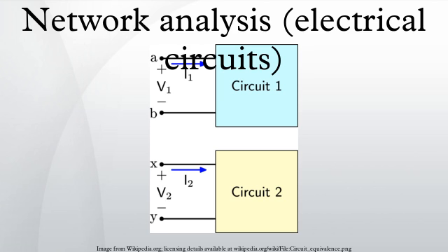Time varying components. In linear analysis, the components of the network are assumed to be unchanging, but in some circuits this does not apply, such as sweep oscillators, voltage-controlled amplifiers, and variable equalizers. In many circumstances the change in component value is periodic. A nonlinear component excited with a periodic signal, for instance, can be represented as a periodically varying linear component. Sidney Darlington disclosed a method of analyzing such periodic time-varying circuits. He developed canonical circuit forms which are analogous to the canonical forms of Ronald Foster and Wilhelm Cauer used for analyzing linear circuits.